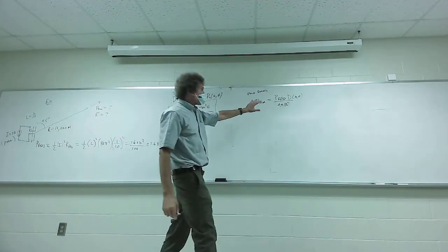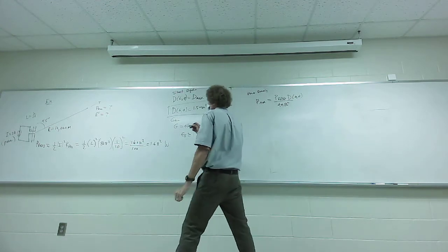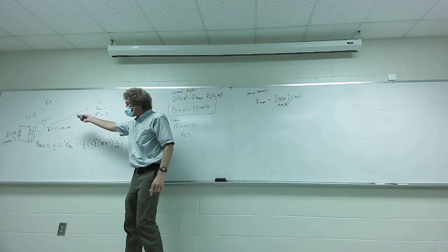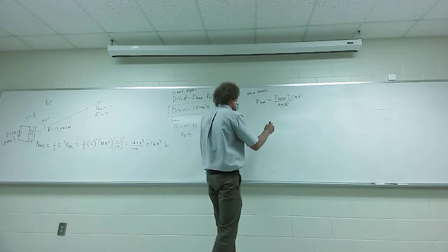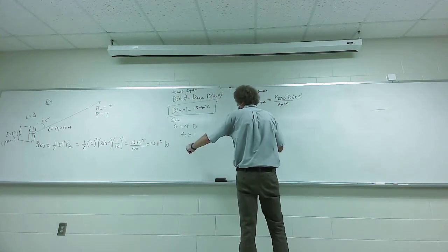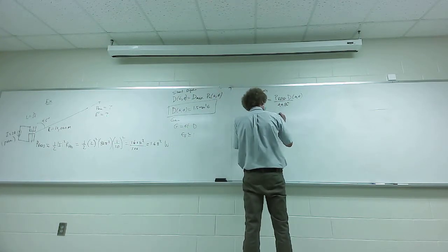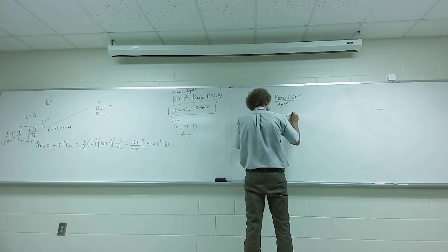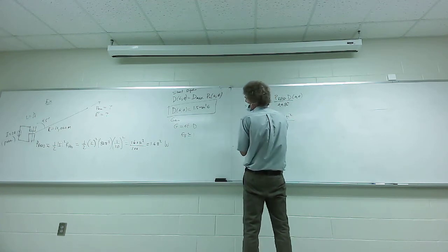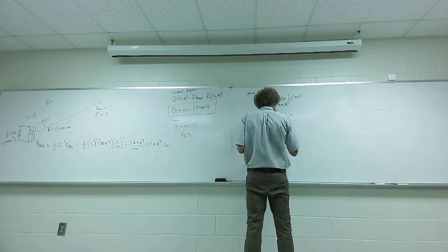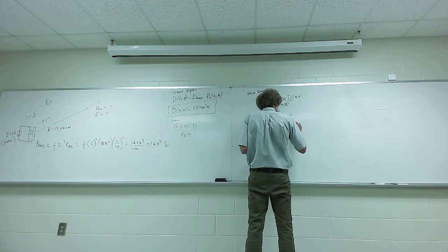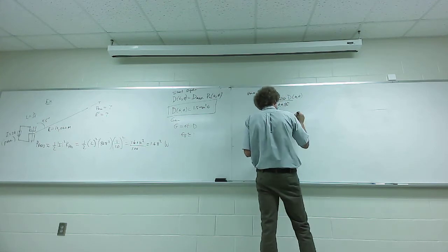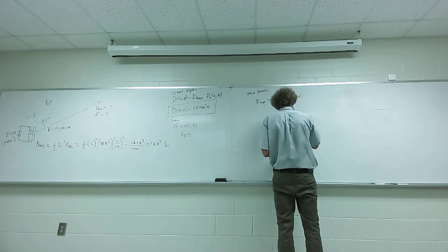All right, now I come over here to get the average power density, because that's the first thing I asked. I give you a range and an angle, right? So I have my power radiated, which is 1.6 pi squared. Then I divide by 4 pi r squared, where r is 10,000 or 10 to the 4th, squared, right? Then multiplied by the directivity.